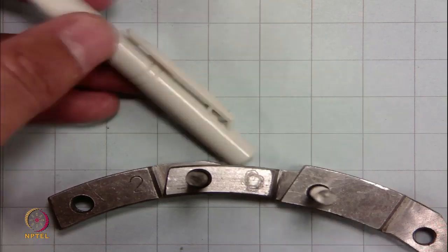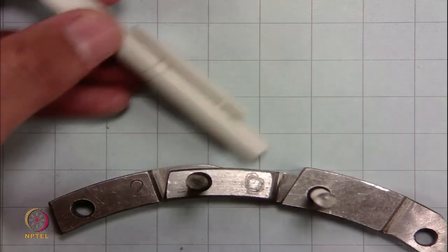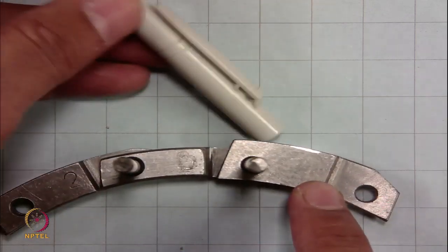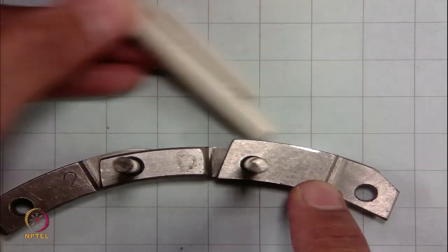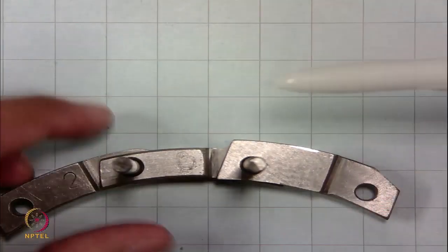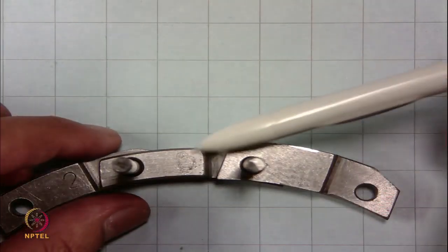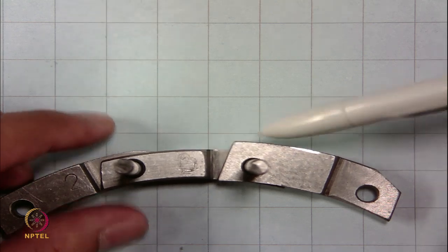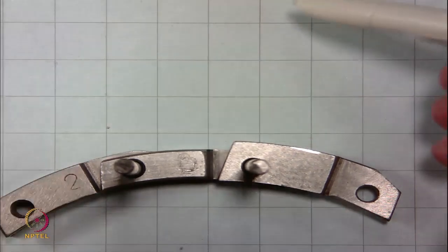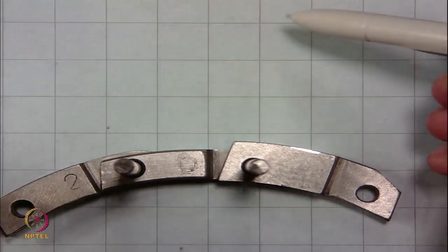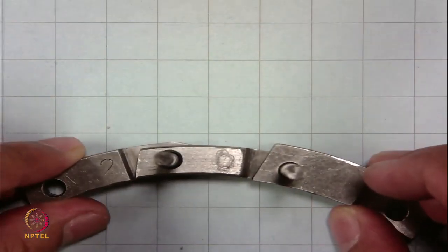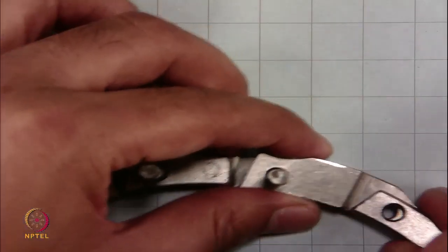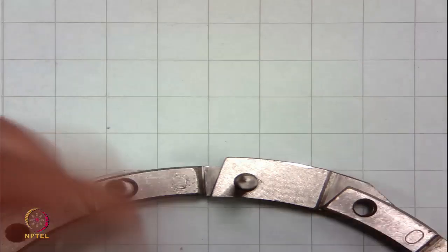So, here the guide bar goes down, and once these links come, again it has to rise. So, whatever the distance is between the elevation of these two guides decides how much lateral shift is happening in the guide bar. Okay. So, that sequence can be decided depending on the fabric design.